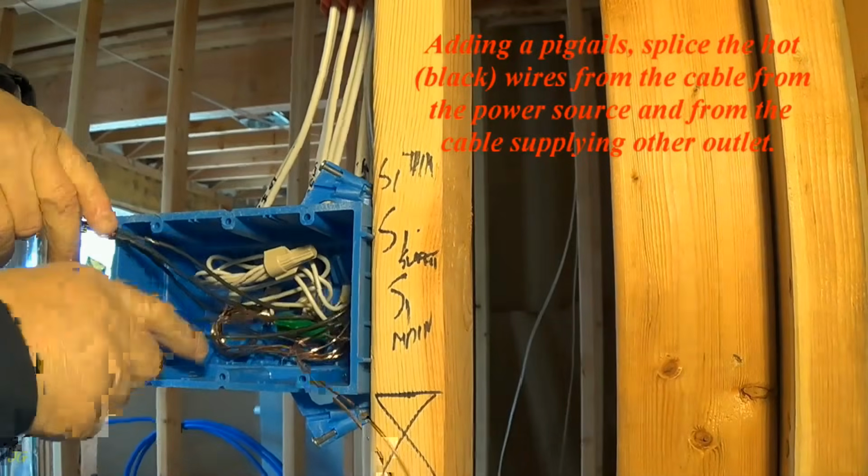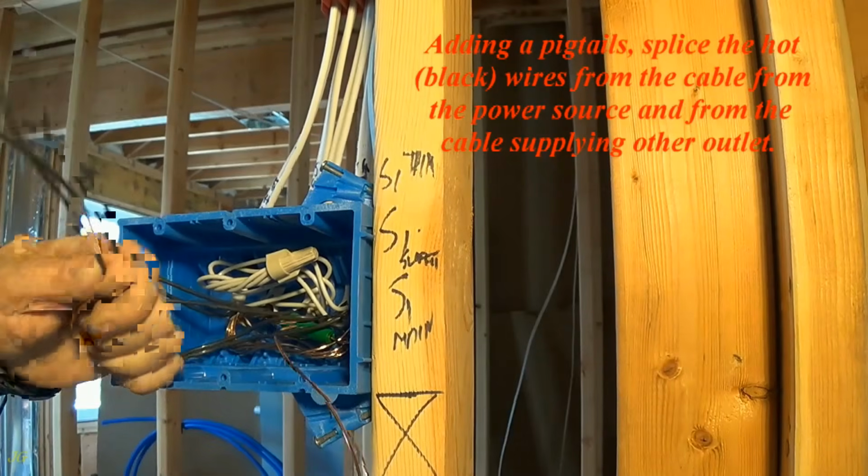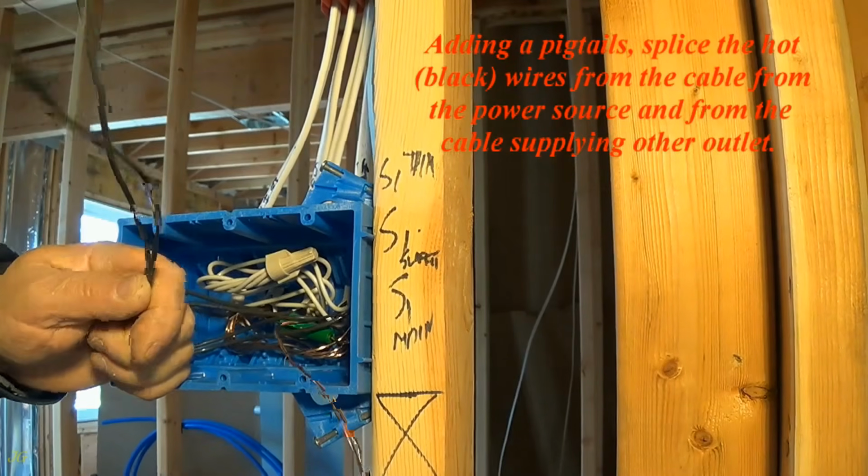Adding a pigtail, splice the hot, black, wires from the cable from the power source and from the cable supplying other outlet.